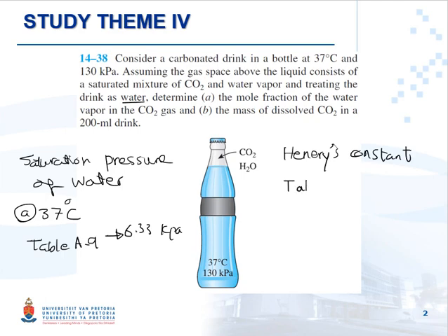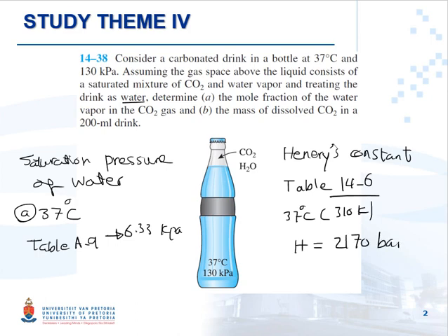You need to go to table 14.6, and for carbon dioxide dissolved in water at 37 degrees, which is 310 Kelvin, H is equal to 2117 bar.